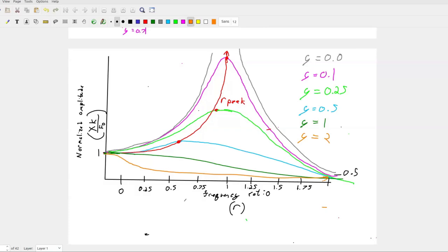If you have an underdamped system and you start to oscillate it, you can get some good displacement, like a swing or like a spring that you're shaking a little bit, right? But if you've got a rod in your hand and you're trying to get a lot of displacement and it's very stiff, you get the most displacement by simply moving it. The vibrations itself aren't adding displacement to your system.